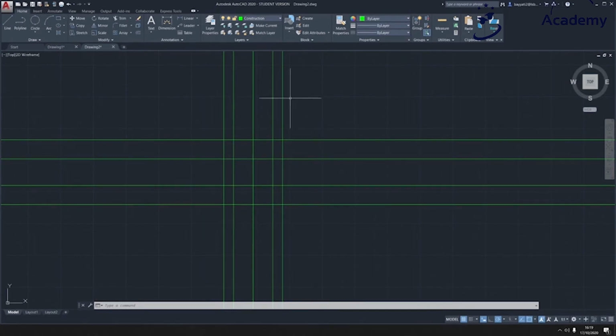So I'm now going to change to the holes layer, and select holes, and I'm going to go to the circle tool, and go to center diameter, and you see it snaps to the intersection of these lines. So I'm going to draw a circle of 20 here, and then a circle of 20 here, and then it says that the bottom circles are 16. So here is 16, then I'll draw one, and I'm going to select that and just use the copy tool. So I'll go to copy, select the center and copy it to the locations we need.